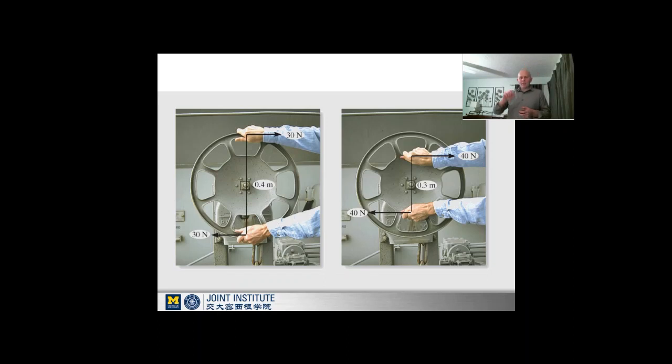Now we can apply the same moment in a different way by applying a larger force at a smaller distance. That might not be the easiest thing to do, and it's much less efficient, but we could apply 40 newtons at 0.3 meters, and that would give us the same moment. So it would be much easier to come out to the outside or an even larger distance and apply a smaller force to rotate that object. And that's a force couple.